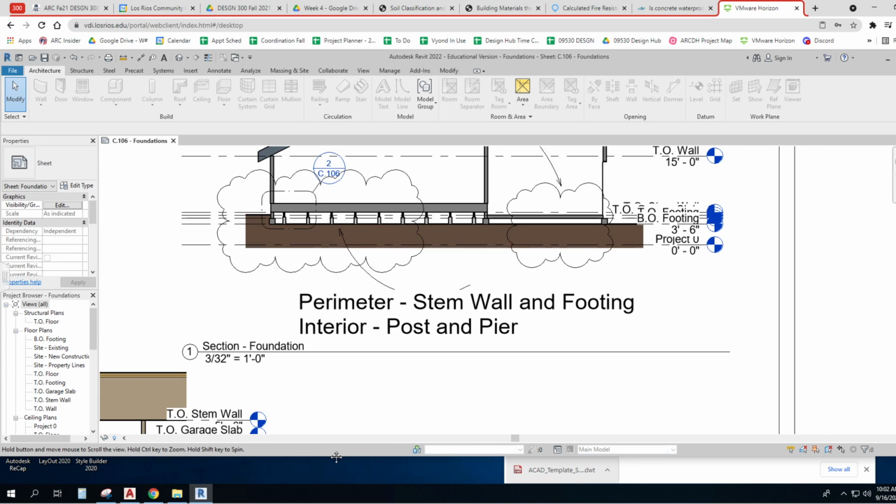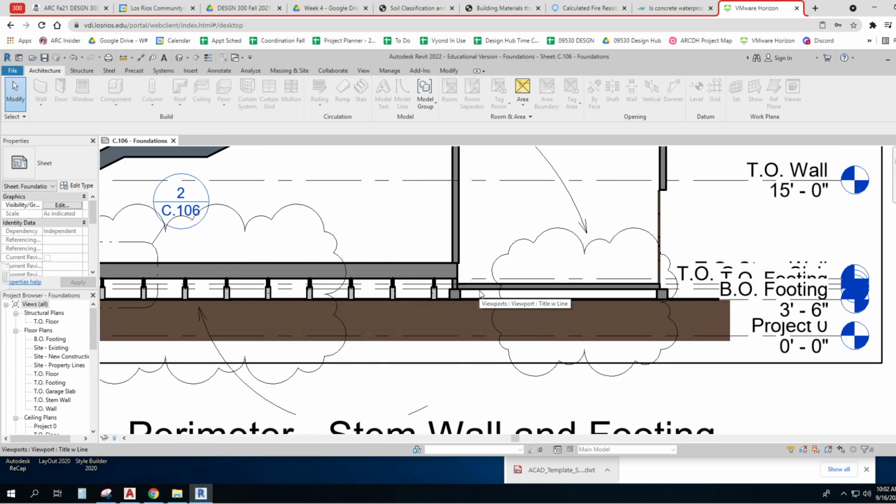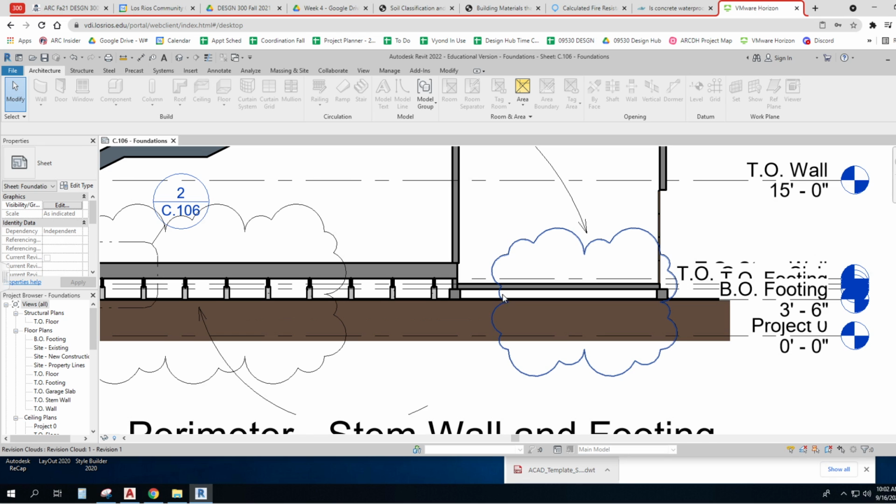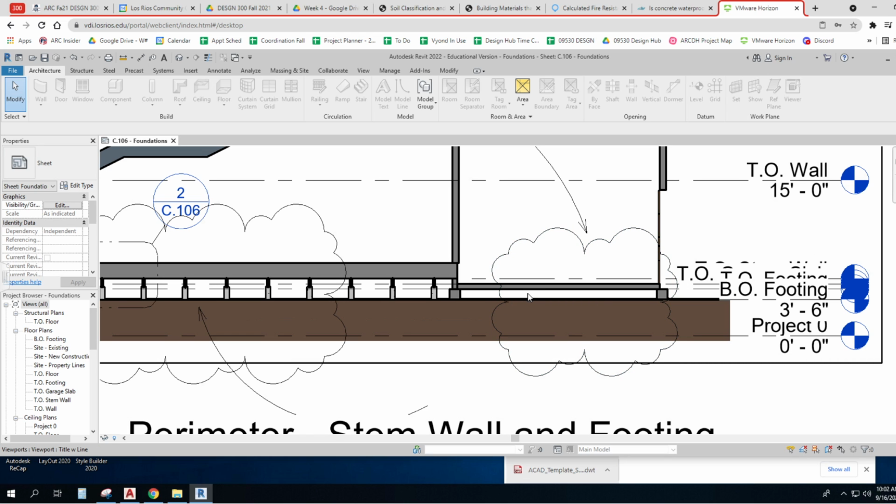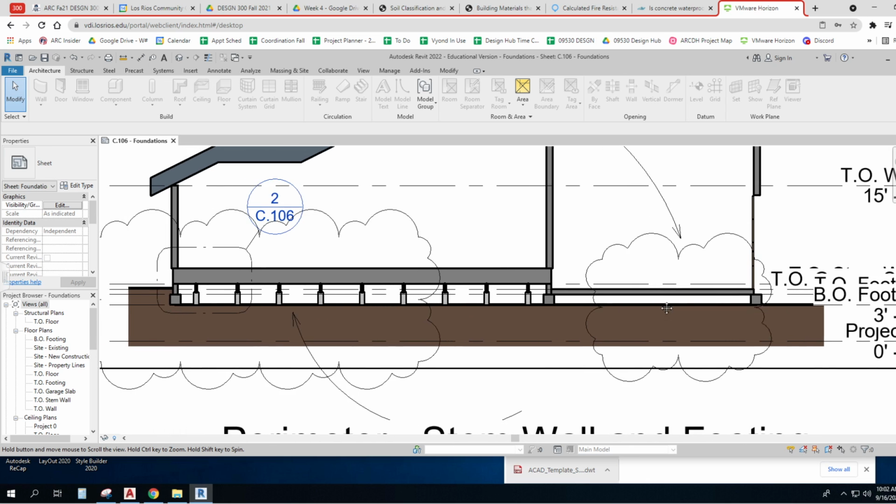So there's dirt underneath the slab, so they call it slab on grade, and that's very common. We do that especially around here with garages and things that have to carry kind of a load, because 4 to 6 inches of concrete spread out is really cool. But of course, it's not very flexible and it tends to crack.